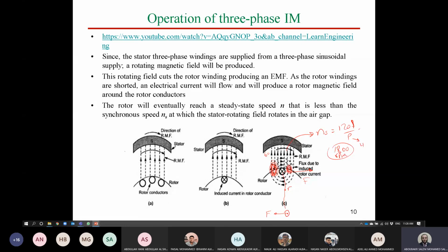Guys, when the machine is at standstill, what will be the frequency of the current? I think exactly the same. It's like a transformer now, right or wrong? This is like a transformer because there is no motion.